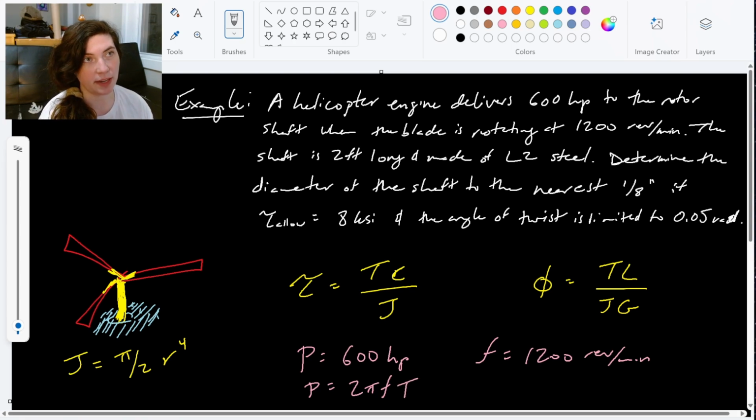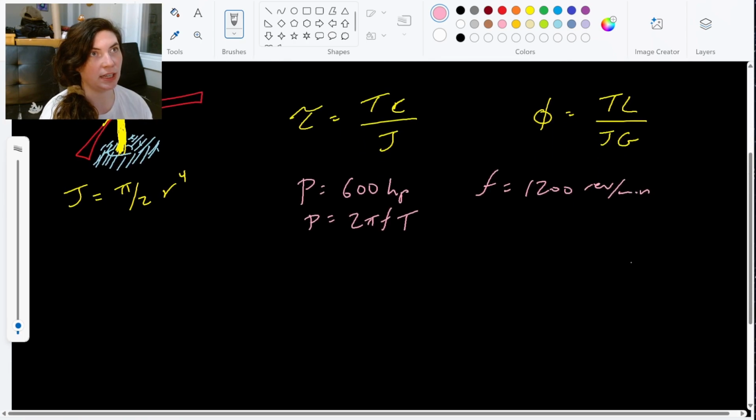And then getting the units right. The units can be a real pain because we love putting everything into horsepower. That's what you see things rated at. That's what's going to appear on your problems. You're going to have to know that 1 HP is 550 pound-feet per second. It comes up all the time. You're just going to have to know it for this class or put it on your note sheet, just wherever you can to remember that.